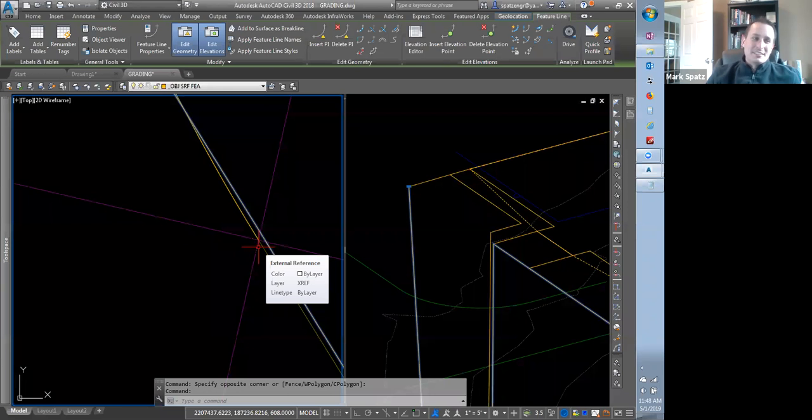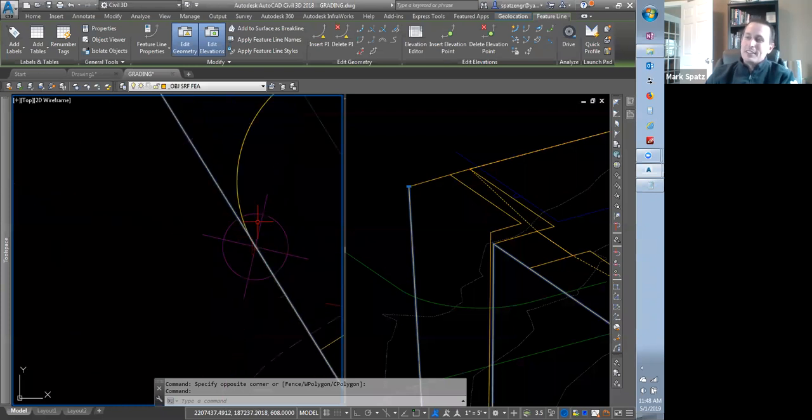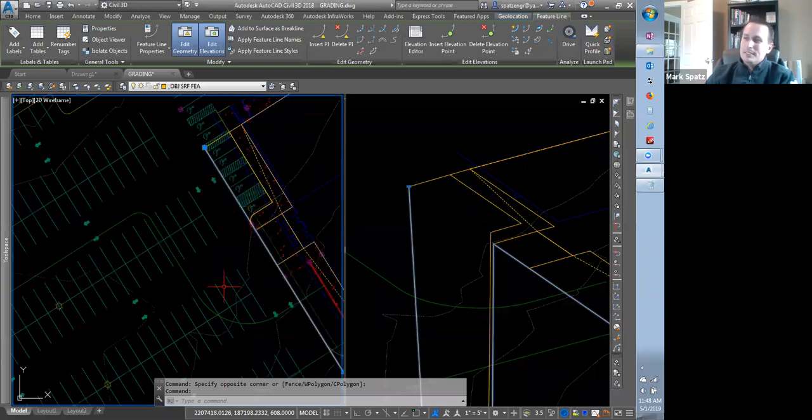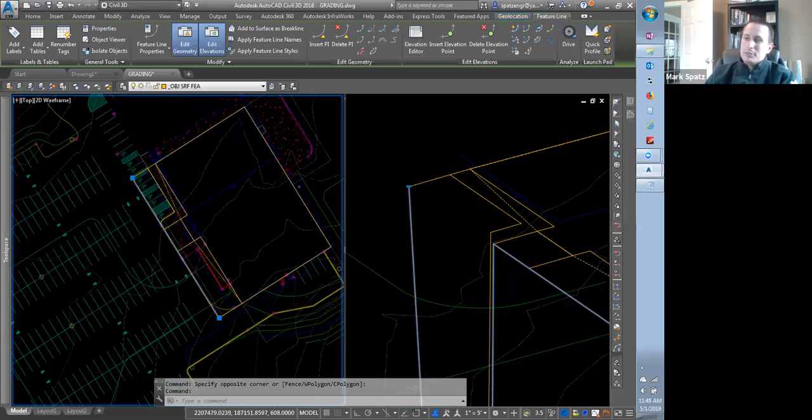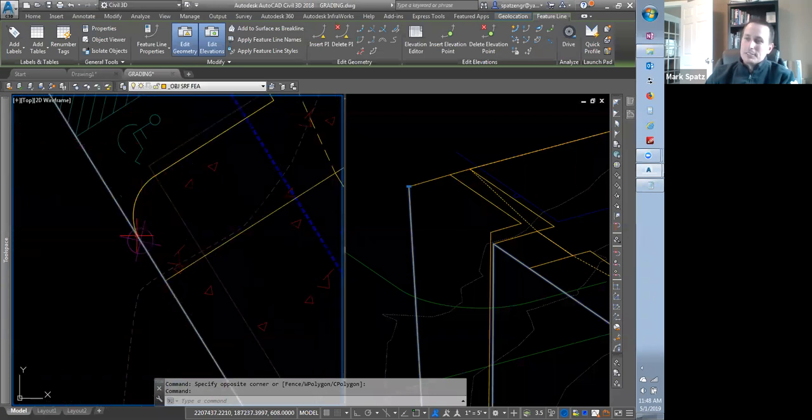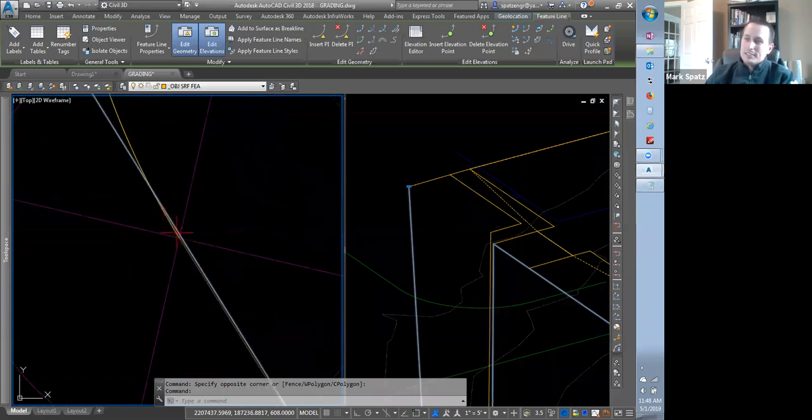These parking lot aisles aren't 90 degrees, and then you measure them, and they're like, they're 90 degrees. They're like, no, they're 90.00125 degrees, which shows up when I'm retracing everything out with the grading objects. So it's important to have accurate geometry. I don't know why that would be like that here, but this offset, that's why that happened.